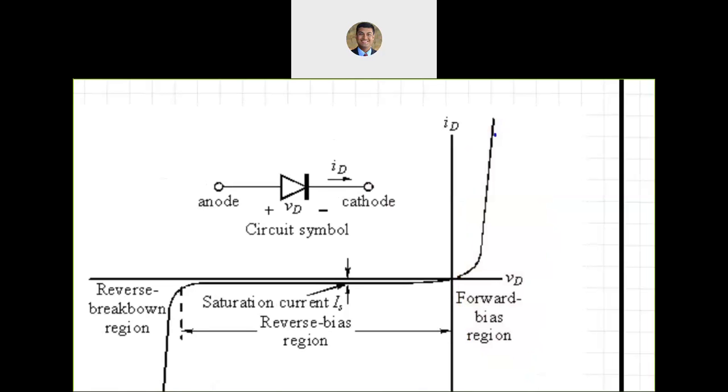I'm going to be focusing on this forward biased region. What are some of the things that I'm going to worry about in this? Well, what is the voltage across the diode here? It is small, but in the positive direction. So 0.1, 0.2, 0.3, 0.4, and at some point the current through the diode rises exponentially, very dramatically. But beyond a certain voltage across the diode, we are not able to explore that region.